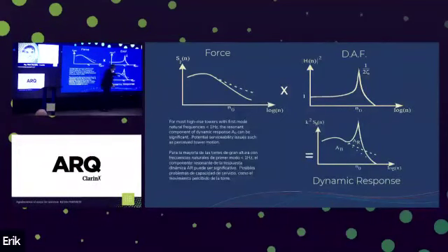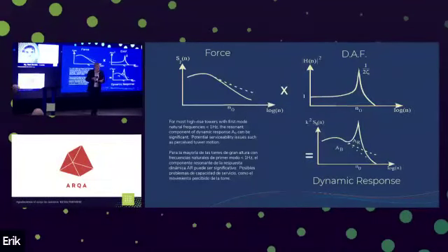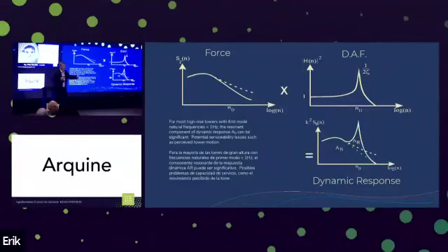So whilst we have a large background component, that's low frequency drifting of the tower backwards and forwards, there can be very significant resonant response, and there can be significant resonant response in the serviceability range of wind speeds. And this can impart motion on the tower, which is an acceleration that can be perceived by humans. And there can be perception of motion problems in high-rise towers. And a lot of the work we do is with high-rise to anticipate this and design out any potential motion problems.